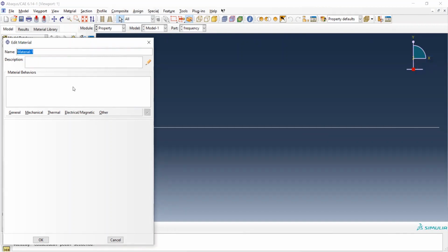And now we use inches as the basic unit. The force is pound force. And the Young's modulus I give you is 209 gigapascal. And gigapascal is an international unit, so we cannot use it here. If we use it here, your answer will be totally off from what it is supposed to be, okay? Because we need to be very, very careful and be consistent.